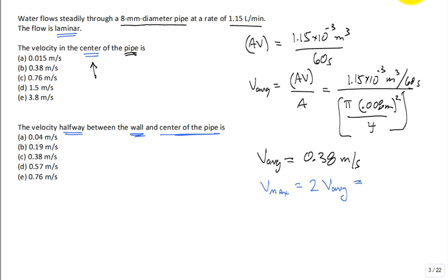All right. So is the equation that V is a function of r or U is a function of r? Jump back and forth, unfortunately, between V and U for velocity, but it's down the x direction of the pipe. Is that equal to V max times 1 minus lowercase r over cap R quantity squared? True. All right. If you're halfway between the wall and the center, is r over cap R equal to 1/2?